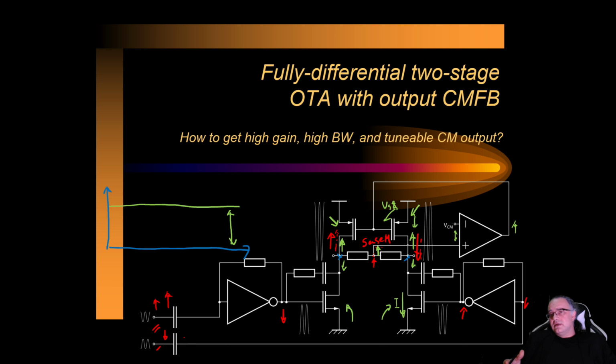Now I change here the common mode to 0.4 volts. So there is a positive delta, which is amplified by the gain of this stage to A times delta, and will lead to raising this voltage. And as this voltage gets higher, then the source gate voltage that I have here in the current sources will get smaller. As this gets smaller, this current reduces. This current in the nmos is just constant, so we don't change it. This is just what these nodes are.